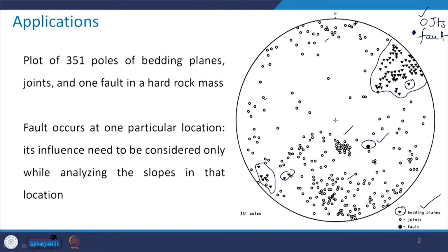Now, how have we plotted these? In the field you go, do the exploration, note down the dip direction with the help of a compass, then come back to the lab or the drawing studio, and plot all that data on this stereo net, and you will be able to get this type of plot, or this type of graphical representation, of all the geological data that you collected in the field. What next? Next comes the analysis. We will see how these are helpful.